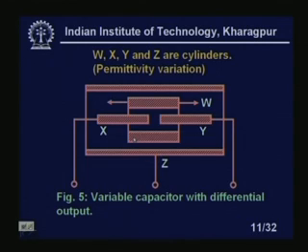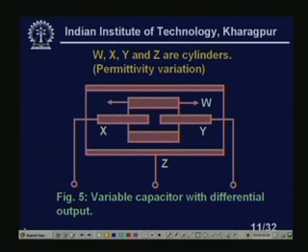Similarly, if this dielectric W is shifted to the right hand side, then what will happen? If I shift this to the right hand side, the capacitance between Z and Y will increase because I am getting more dielectric medium, and the capacitance between X and Z will decrease because I will get less dielectric medium.